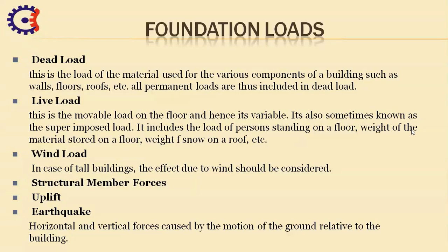Wind load acts on all exposed surfaces of the structure. The wind load may be neglected in designing the foundation unless it causes loads on the foundation exceeding 1/3 of the load due to the dead and live load. Full wind load should absolutely be considered in the design of the foundation of unusually tall and narrow buildings.